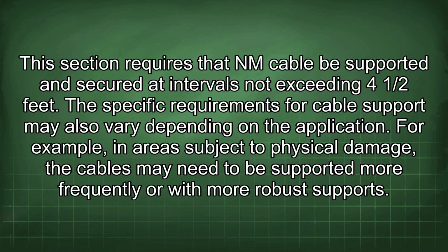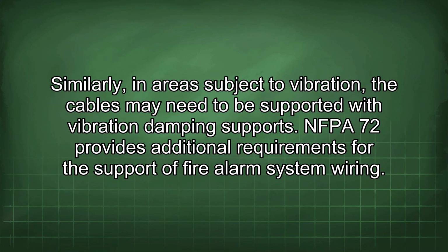The specific requirements for cable support may also vary depending on the application. For example, in areas subject to physical damage, the cables may need to be supported more frequently or with more robust supports. Similarly, in areas subject to vibration, the cables may need to be supported with vibration damping supports.